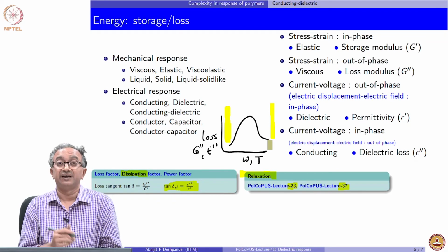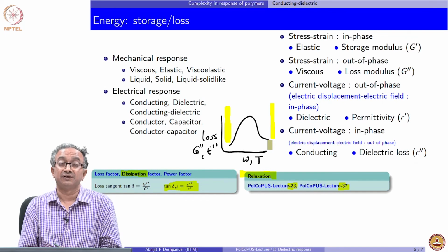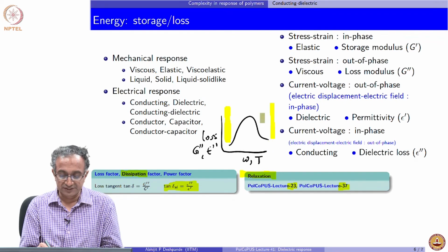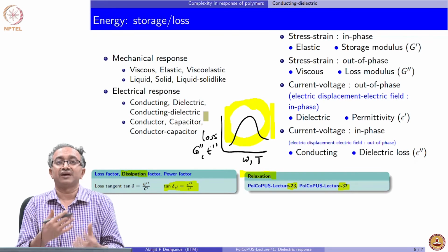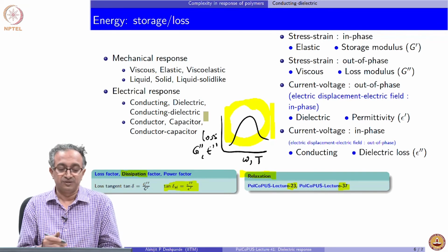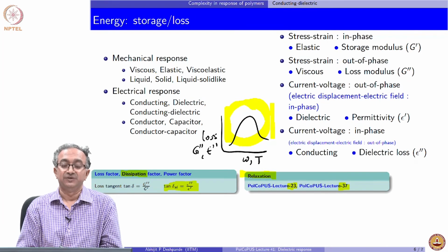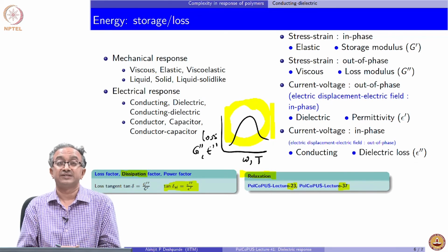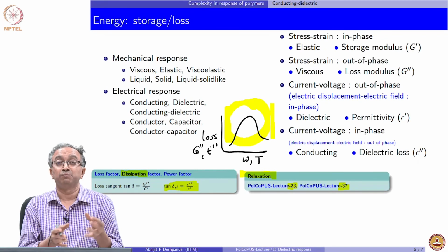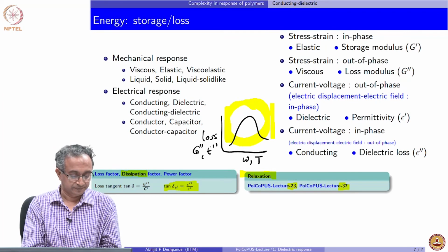Similarly, at higher frequency or temperature, dissipation is again not as high, and it is in between where the dissipation is maximum. This is like a phenomenon of resonance, and it is also the idea behind spectroscopy of these materials. We can apply different frequencies and study the overall set of relaxations present in these materials, and we will do this both for dielectric response as well as viscoelasticity.